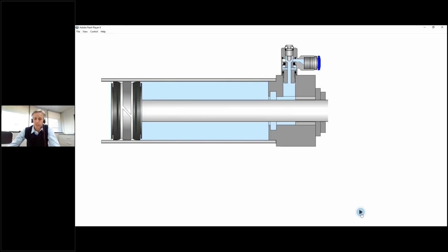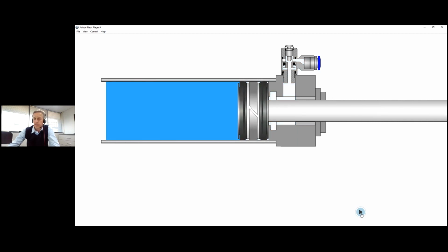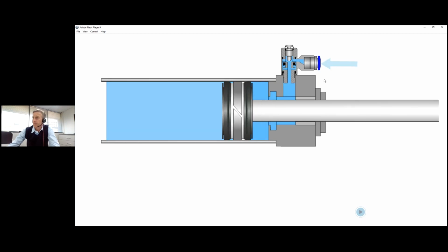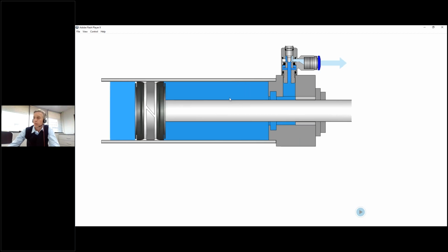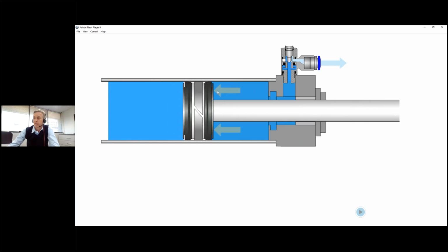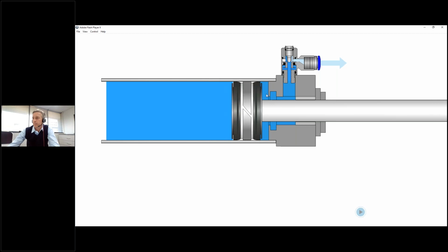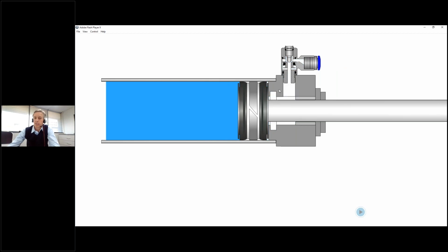All right, so first the actuator is going to be moved forward without any speed control. You can see that. And it can move backwards freely because we're using a one-way flow control valve. Now you will see here is the little throttle. If we move that in, so we set the throttle, and if we actuate the actuator again, you will see the cushion pushing back on the front of the piston. So at the back, you've got your air pressure, and at the front, the restriction of the air is pushing back on the actuator, and that is exactly what we want.